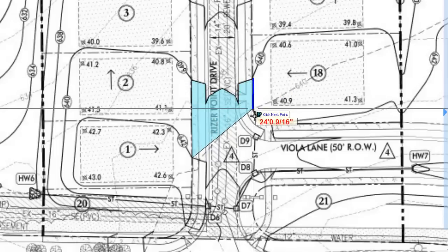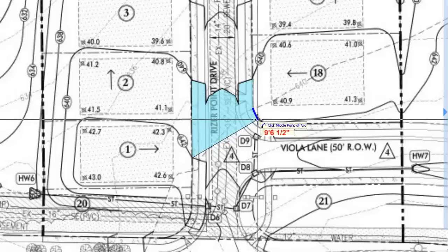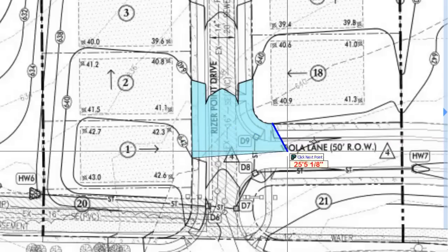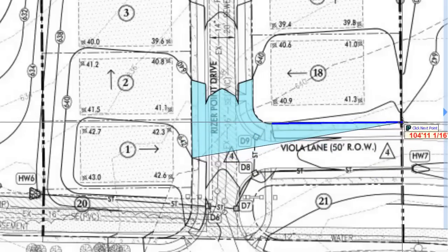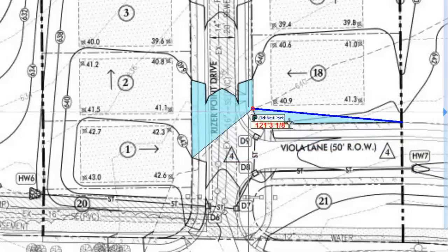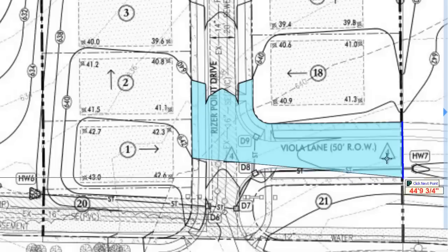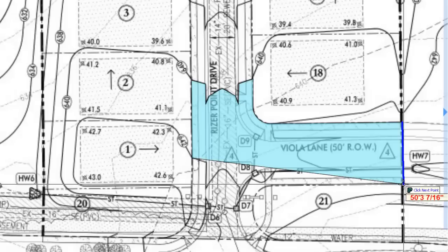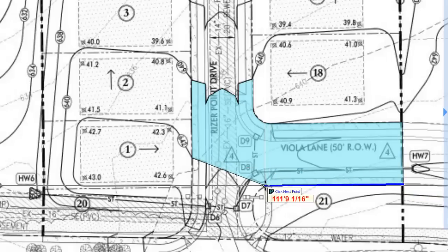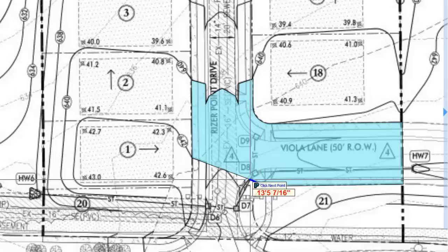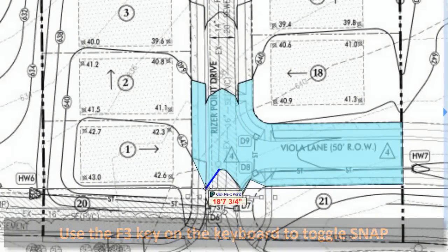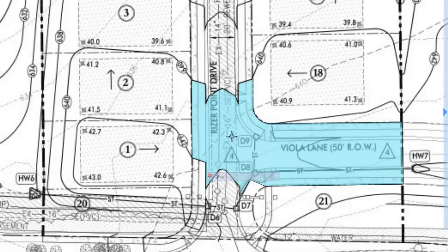And you see I'll come back around here to the road. I'm going to tap A for arc, and I can turn and do an arc through here. And then follow my line out along the road and come back down the road here. I can follow these lines. It's a little tricky. I think this is it right here. And I'm going to turn snap off because it's kind of getting in my way. So I can make that adjustment and do that road section just like that.